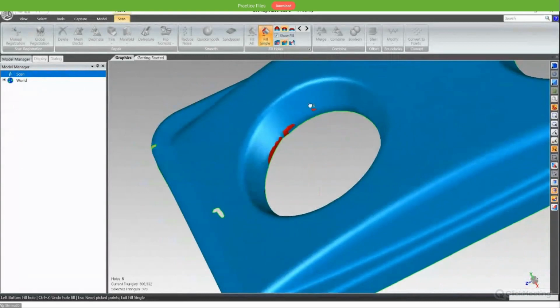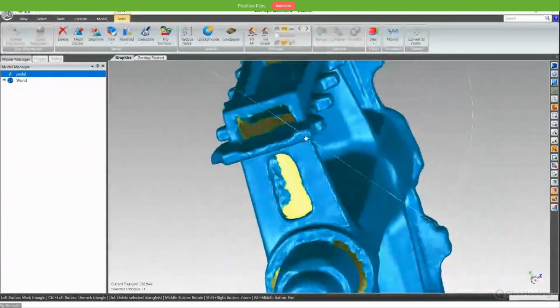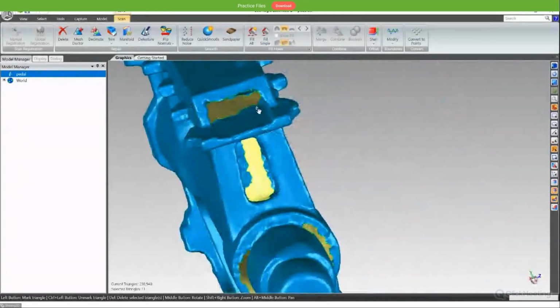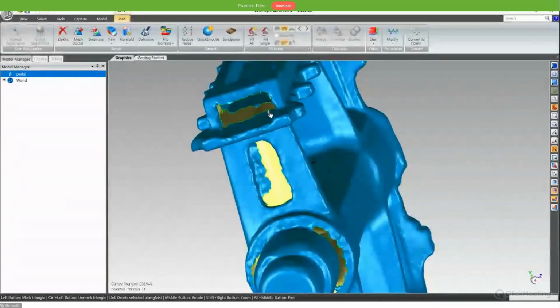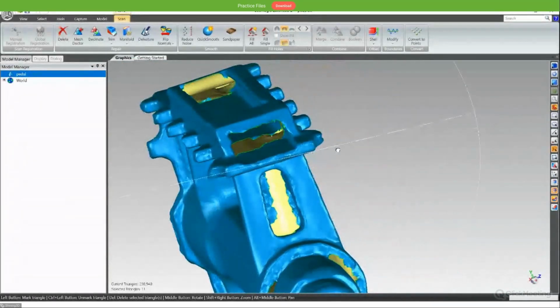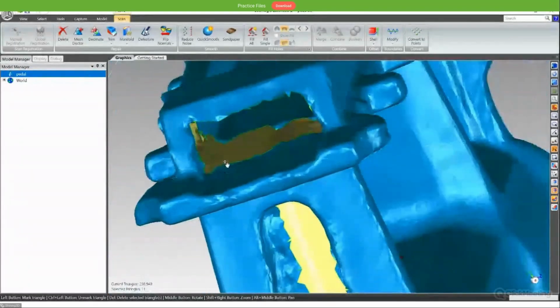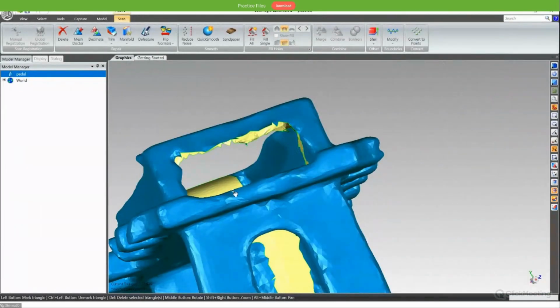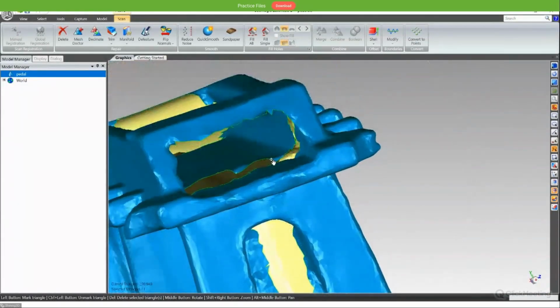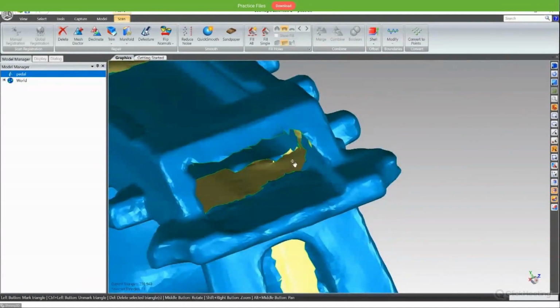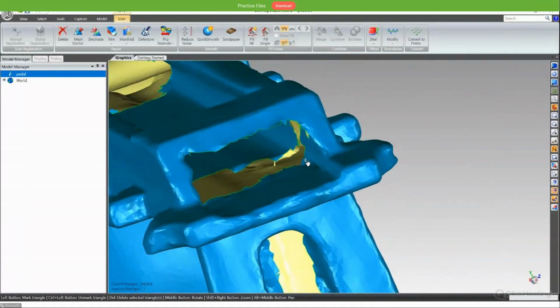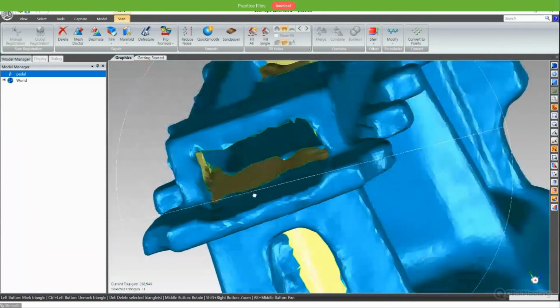And the bridge function. If we choose fill whole or fill partial, sometimes we cannot achieve the hole filling by fill complete or fill partial in some areas like this. If you choose the complete, maybe all the parts will be filled, but apparently we need some edge, the edge on these two sides, right?